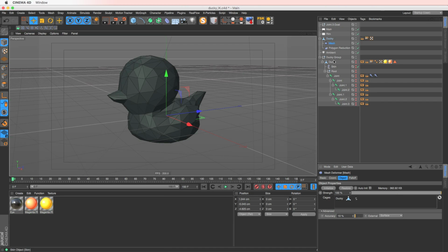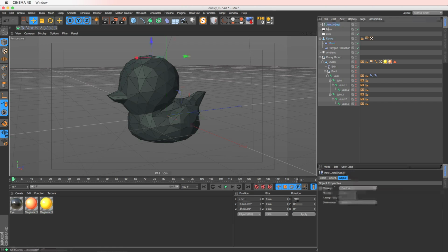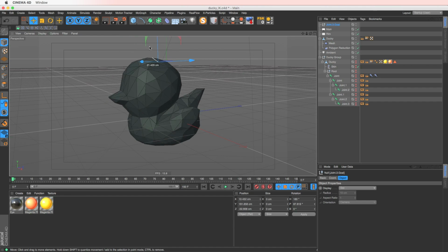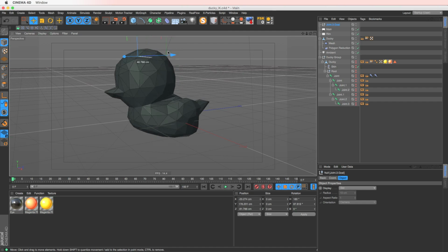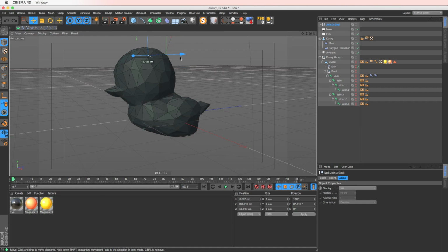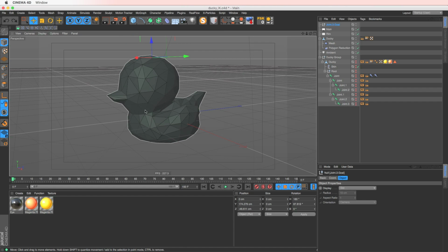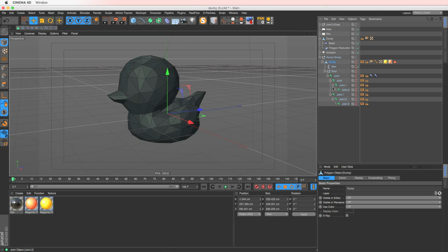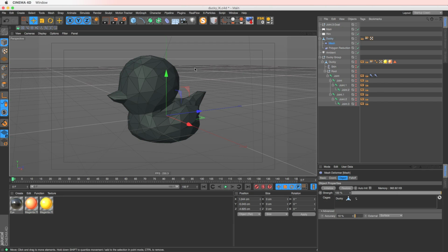And we'll again use surface just in case anything's kind of poking out. Hit initialize. And now if I move my joint goal, you can see that I have my higher poly rigged ducky geometry deforming the lower poly mesh. So we don't need to re-rig and re-skin and re-weight a lower poly mesh. We can just use the existing ducky mesh with the skin deformer and the joints to have it drive a lower poly version of that.